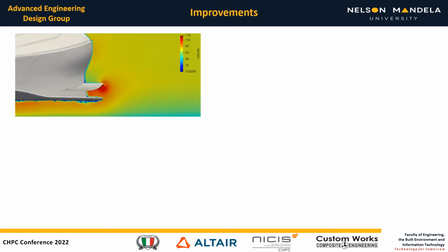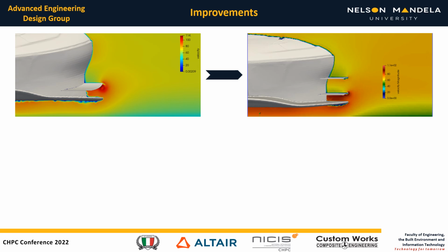My initial thought was not to reinvent the wheel, but rather just to check if it was in the optimal position. I varied the height of the dive plane on the vehicle until the most efficient position was achieved. I measured efficiency in terms of lift over drag and found that by moving the dive plane down 120 millimeters increased efficiency by 1.4%. I then doubled up on dive planes, which boosted my increase in efficiency to 2.2%. I also added a curve at the side to help reduce the spillover of high energy to low energy zones from above to below the dive plane.